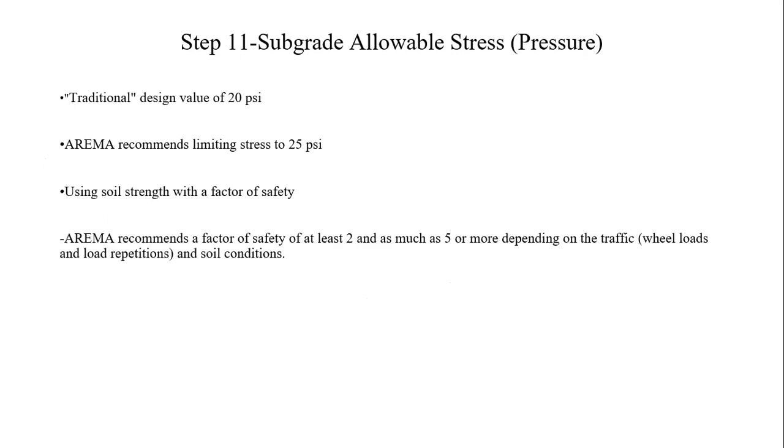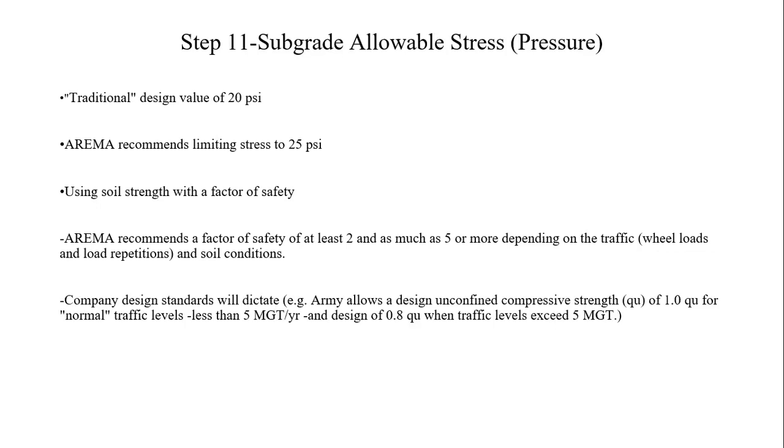Now, typical values: the allowable subgrade stress is 20 psi, and the AREMA requirement is 25 psi. It uses soil strength with a factor of safety. For that, AREMA recommends at least 2 and as much as 5, depending on the traffic and wind load. Company design standards will dictate how much load.